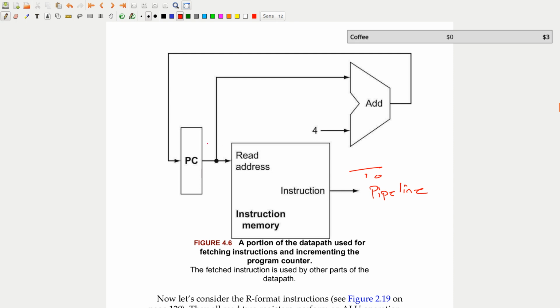Then we take this program counter value, we increment it by 4, and then this will become the address of the next instruction. As we saw earlier, this gets a little more complicated if we have, say, branches that aren't the next instruction but maybe behind the previous program counter value or farther than one instruction away from the program counter value. So we'll have to change a little bit to handle branches, but if we're just doing things in order, this works pretty well.